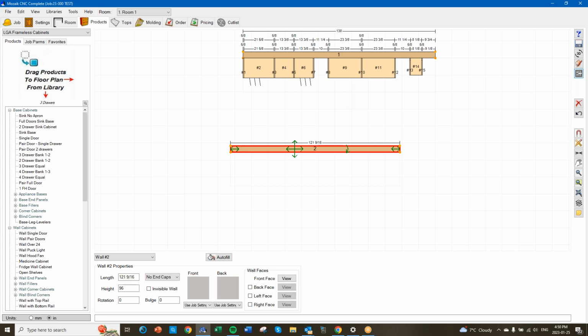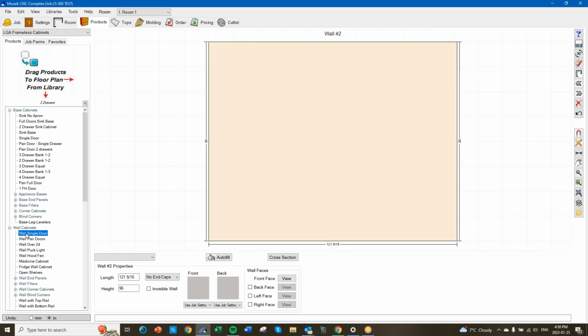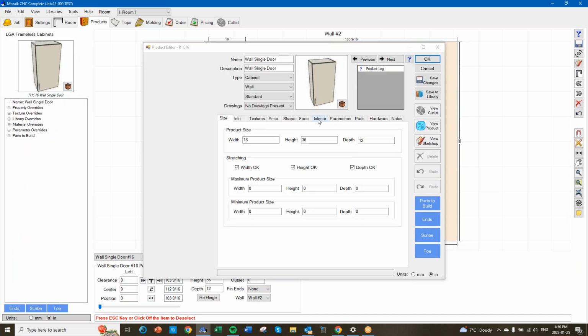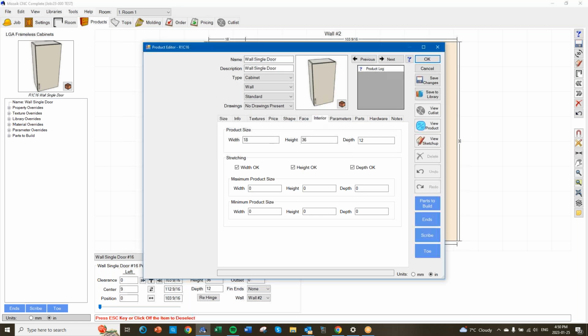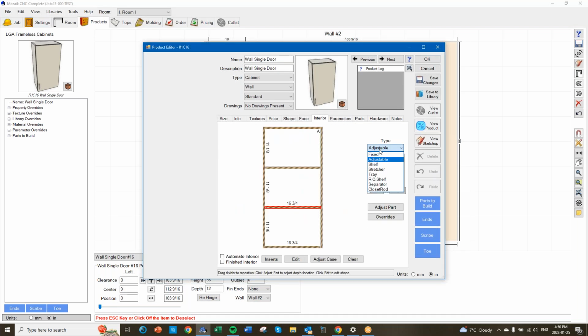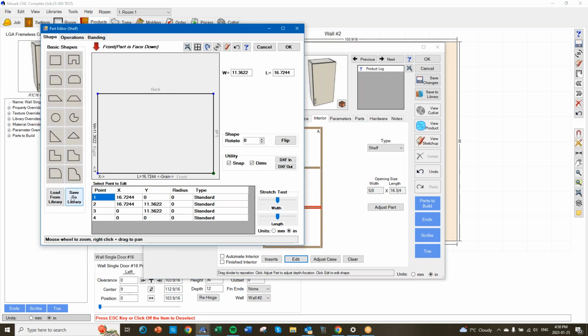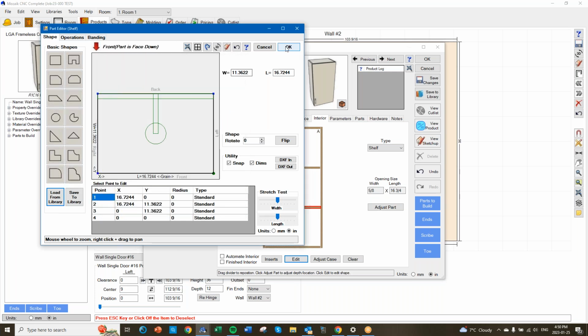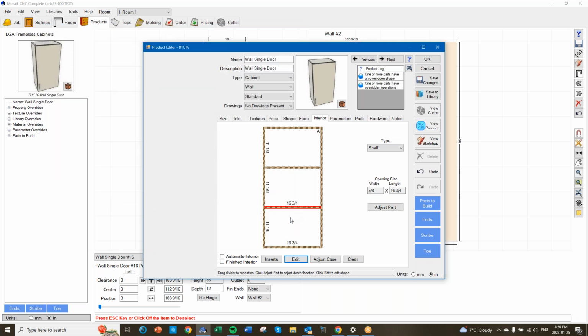Yes. Very, very quick. So I do this cabinet here, right? I edit, put an interior, put a shelf, I transform this to a shelf. And then I come edit, load from library. Library, I get this guy here. And then it will create this puck light shelf. Now, I don't have that one for the corner cabinet. Can we create one for a corner cabinet?